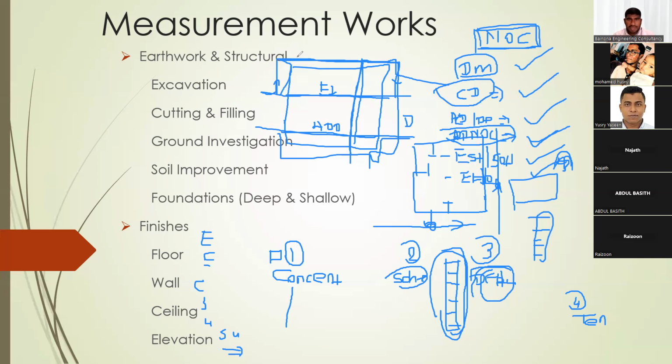Pre-contract stage, when we are preparing the bill of quantities with no price. Yes, so it means the consultant is preparing the bill of quantities, and we will mention this is a PC rate. After client change, for example, tile PC rate, it will come as a variation. Pre-contract stage time only, we can allow the change of PC rate to client. Or he can sign the contract later stage, he can change the PC rate as a variation.